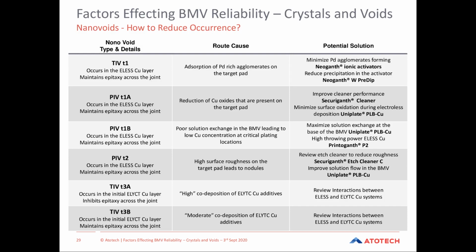And we've also now introduced pre-dips, which are more compatible with the ionic activators. They stabilize the baths better. They reduce the agglomeration, they reduce the precipitation. And those customers who are running it are definitely saying they get less palladium-related defects within their products.